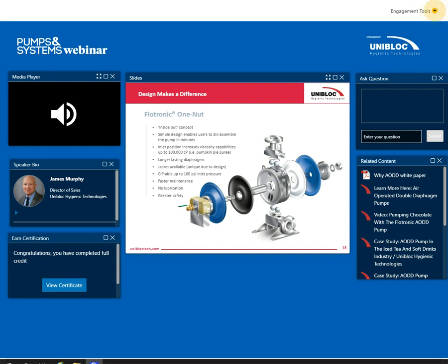Great. The next question is, is the pulsating cycle on the pump discharge subtle, less than 1 second peak to peak, or noticeable, greater than 1 second peak to peak? Yeah, so that has a lot to do with the product you're pumping and how fast you're actually running the pump itself. At a very slow speed, the product kind of comes out like soft serve ice cream in a piston filler. I'm sure you've seen that before.